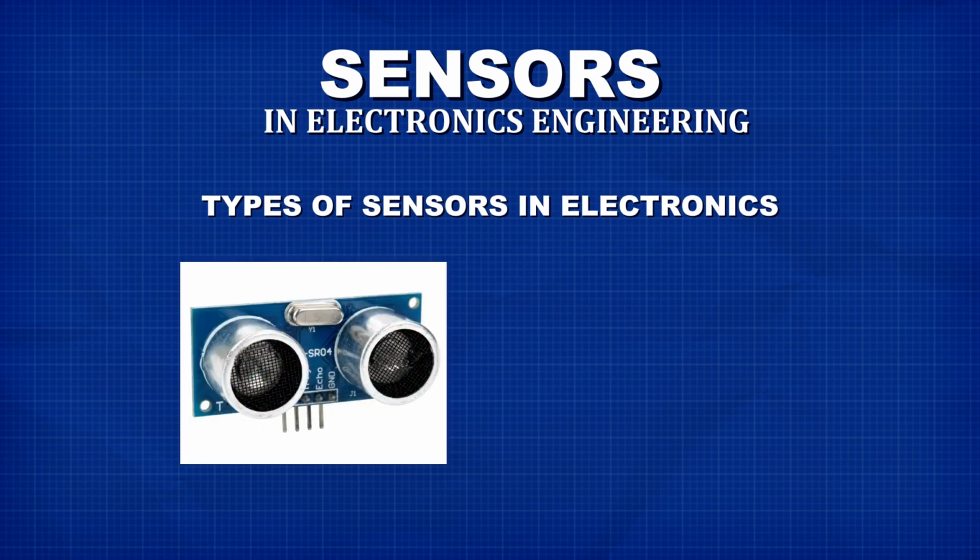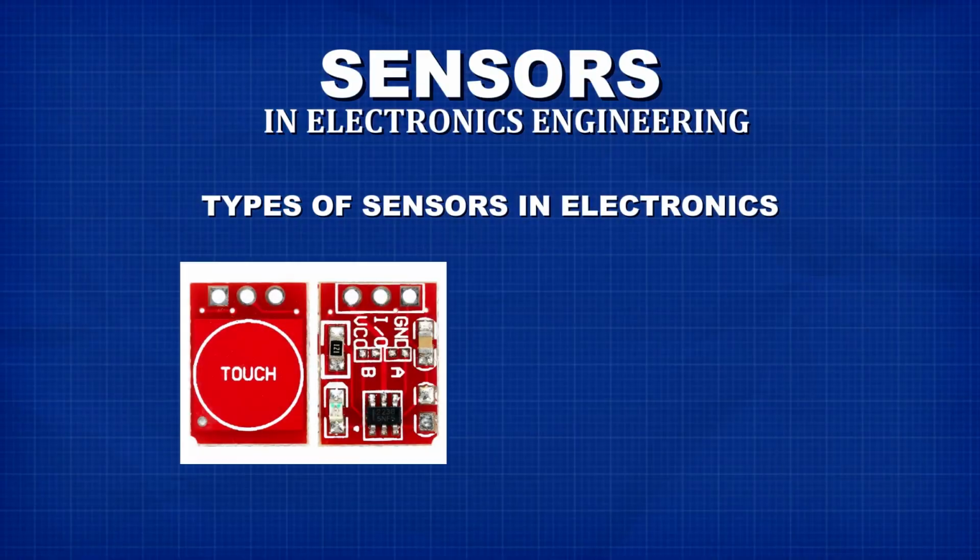3. Ultrasonic sensor. An ultrasonic sensor is used to measure distance. It sends out sound waves and waits for the echo to return. By measuring the time it takes for the echo to return, it can calculate distance. This type of sensor is common in robotics, obstacle detection, water level measurement, and smart parking systems. One common example is the HC-SR04 ultrasonic sensor.